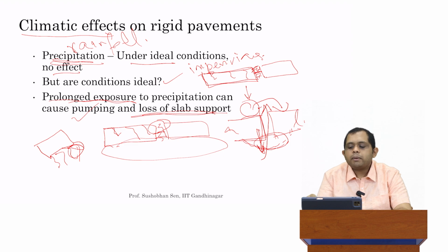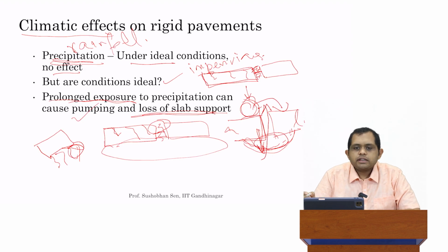You will note that while pumping requires the presence of a load, the loss of moisture support does not require the presence of a load. So pumping is largely caused by a climatic effect, although an external load is also required. So that's the effect of prolonged exposure.